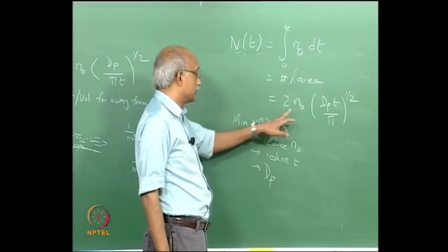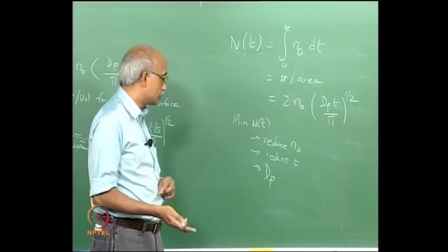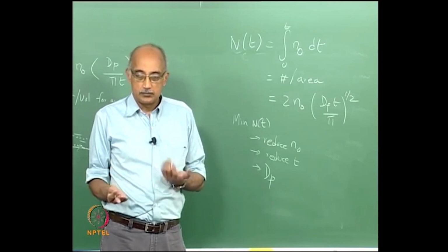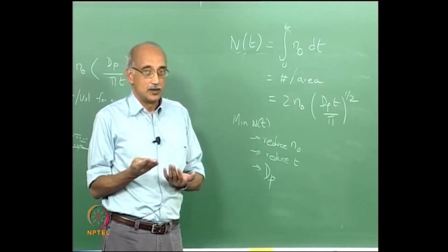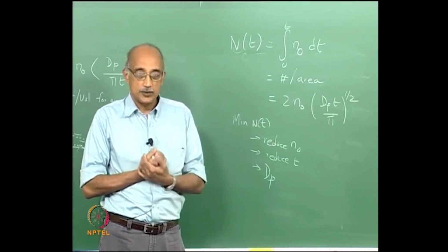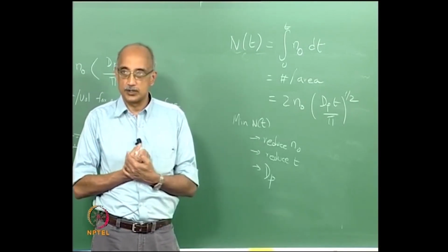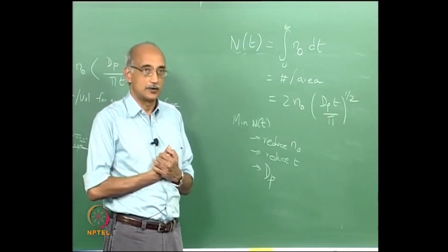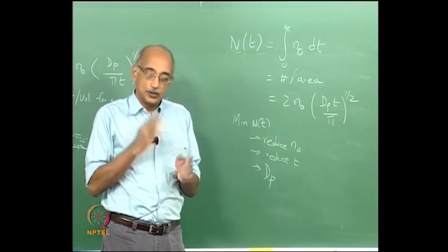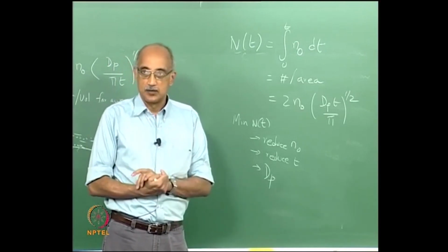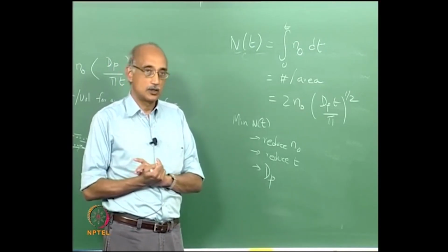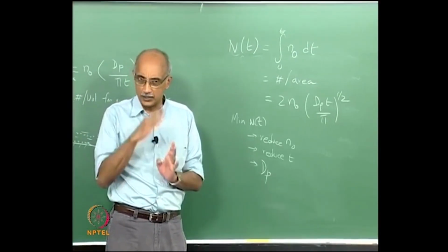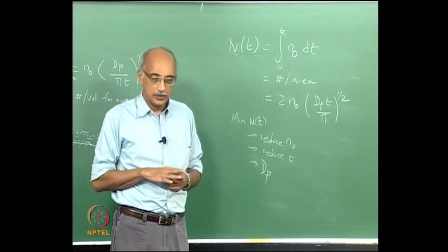What you want to do is minimize the diffusivity of the particle. How do you do that? By having larger particles in your system. But is that a smart strategy? As particles become larger, yes, the diffusion rates will slow down, but all these other transport mechanisms will start kicking in, right? So you may be reducing some of your diffusional fluxes, but at the cost of increasing your convective fluxes, your inertial fluxes, and so on. So you have to think about it in a more systemic fashion.